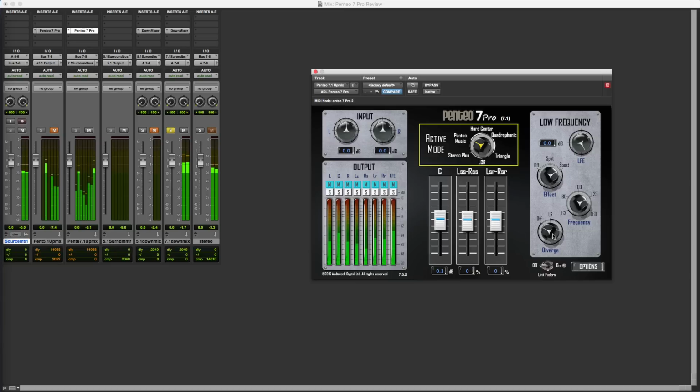So we can set this diverge mode on, and that redistributes the LF boosted content into the left and right channels. So it spreads it out, so it's less likely to distort the center channel. We've got the option to now effectively work out where the turnover is, where the boost point is. So if you consider almost this as a low frequency shelving boost.